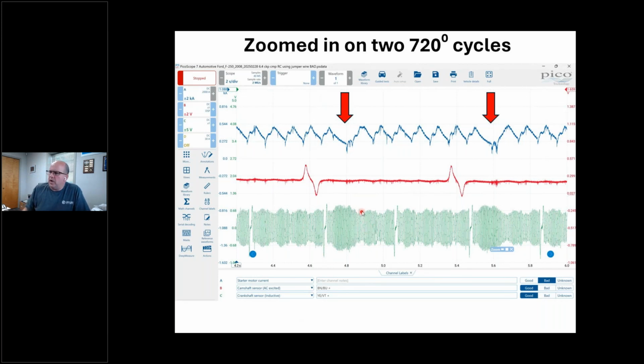And look right after it. You see it kind of slowed down, because guess what? That crankshaft sped up because number 4 doesn't have any compression. We don't know why yet, but number 4 doesn't have any compression. And then the crankshaft got a nice wind up going, and all of a sudden it hit the next cylinder of the firing where it's like kind of hitting a brick wall. Okay. And that slowed the speed of the crankshaft down right here. Okay. So I can make that inference. So that also backs up my starter motor current.